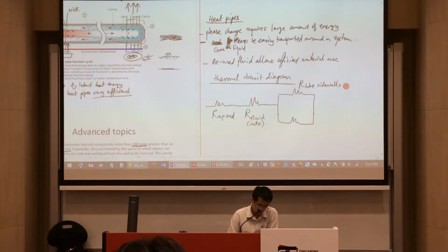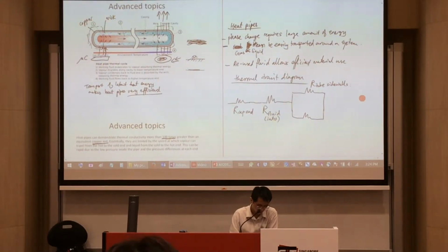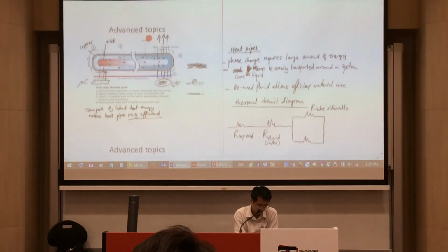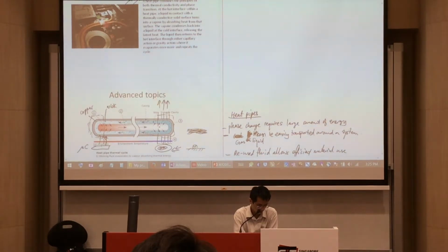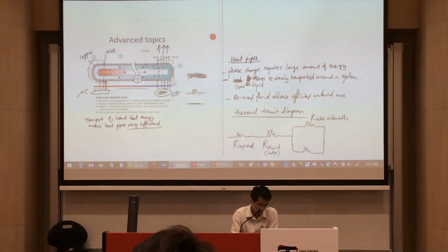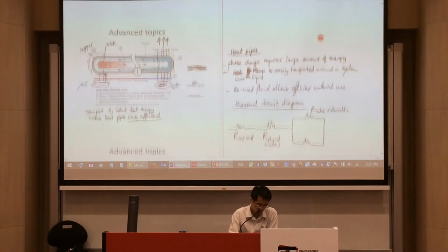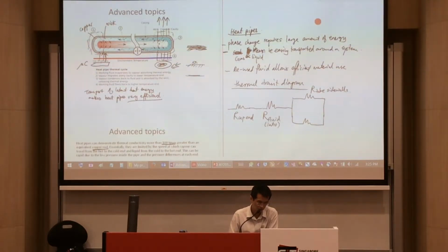You could see for your heat pipe over here, this side wall could also accept heat toward the side. If you notice the figure that I showed you just now, there's no thermal insulator around this surface. It's actually not necessary, and I'll tell you why later. So there's a thermal resistance where heat can actually transfer out.